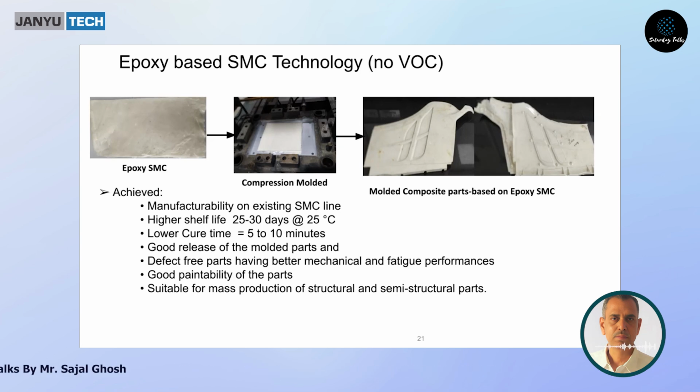Thickening technology is easy for our unsaturated polyester and vinyl ester resin because there is an acid group, the COOH carboxyl group. So when we thicken, the thickener is generally magnesium hydroxide base, or sometimes polyurethane or other hydroxides, or a mix of these.